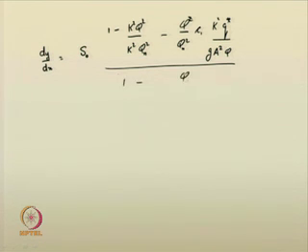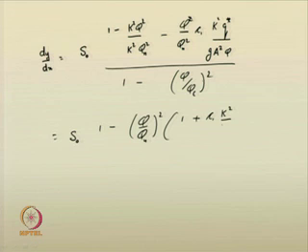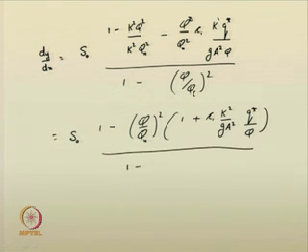This whole quantity divided by 1 by Q by QC whole square. It is in a similar form as you have done for the dynamic equation for gradually varied flow. Almost in a similar way, we are writing the expressions. So, now 1 minus Q by Qn whole square, 1 plus C1 k squared by Ga square Q star by Q, the whole thing divided by 1 minus Q by QC whole square, like this we get.